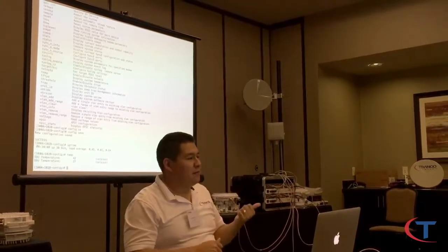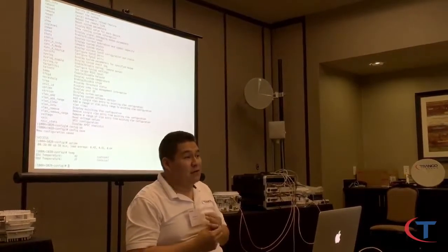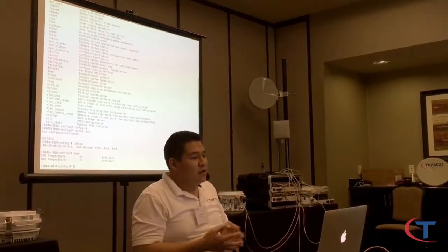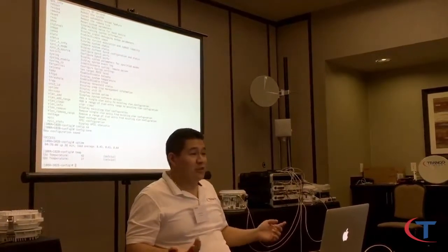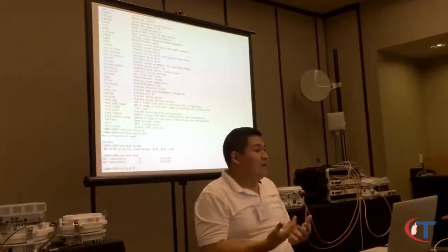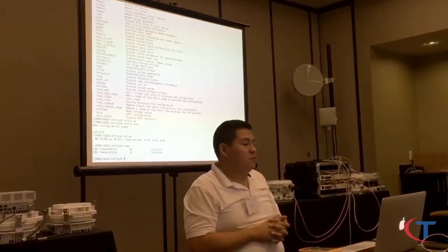IF cable can diminish MSE values and also make ODU transmitters act funny. To me, that was probably a short somewhere related to water entry on the cable. I thought it was bone dry. I didn't cut the cable open again because I didn't want to change it, but that's something for you guys to look at. IF cables are one of the most common problems in split systems. So just keep that in mind.